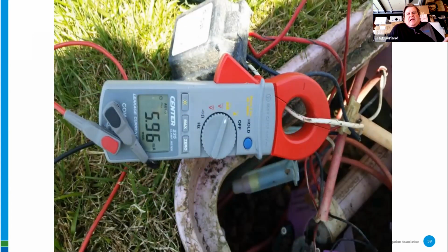So you can do this, and if you're looking at the pictures and following along, there's a huge benefit. My clamp meter does not require me to separate any wire connections. I'm not cutting any wire. I'm not removing wire splices. I just clamp around the wire feeding the decoder up in the top of the screen. Or I'm taking that clamp meter and clamping it around the 2-wire path in each junction box or each connection box. I'm not disassembling anything.